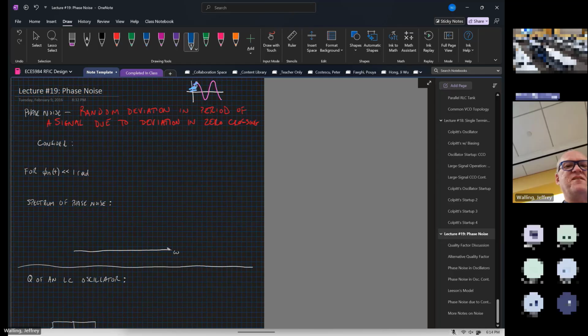So there will be a cloud of uncertainty associated with the sine wave. Now, the mean or the center of that cloud will be where the sine wave should be. But in reality, every point on the sine wave might be deviating from where it should be, and that's just due to random fluctuations that occur in the circuit due to noise. Active circuits have noise, passive circuits have noise, so I never know exactly where the signal is going to actually appear, but I have a statistical idea of where it's going to appear.